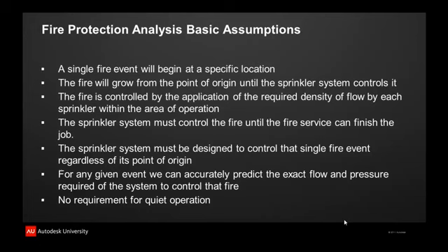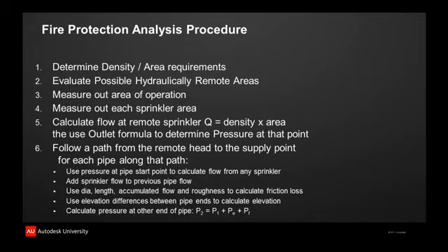I said lastly, but just as sort of an afterthought, there is no requirement for quiet operation. That's a comparison to the plumbing system that's operating all day long with people around. We'd like it to be quiet. Once the fire begins, there's fire alarms and a general alarm that people want to get out of the building. And if there's some noise associated with the operation of the sprinkler system, as I've mentioned before, that's not really a bad thing. So if we take these assumptions, we can put them in terms of the actual procedure that we would use to perform this analysis.